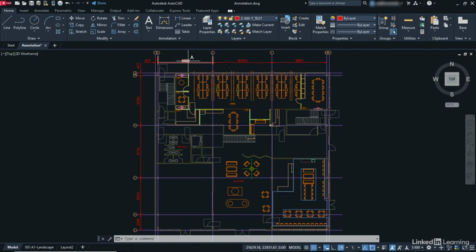Now you'll notice that our grid lines have already got some dimensions. You can see them here, there's dimensions here like so. And you can see they're on a particular layer. So if I hover over one, you can see it's the A010D dim layer. So before we do anything else, we need to make sure that we're on the appropriate layer to place our dimension annotation on the drawing itself. Now, you'll notice we're on the text layer in the Layers panel.